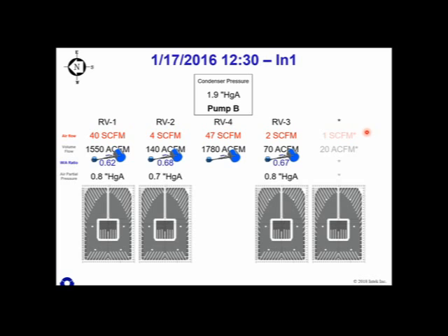And so this is why they didn't believe it. We saw air leakage coming out of this bundle at 40 SCFM. And almost no leakage at all coming from the three other lines, 1, 2, 4 SCFM here. The other reason they didn't believe it was the total flow rate. The total flow rate measured, which is essentially the vacuum pump capacity, was 1,780 SCFM.